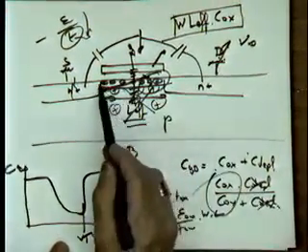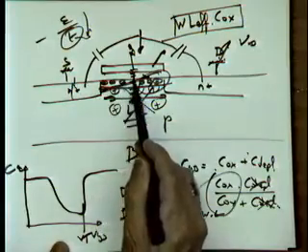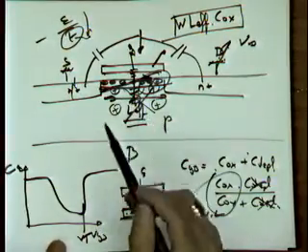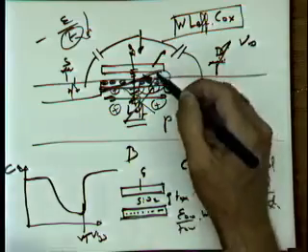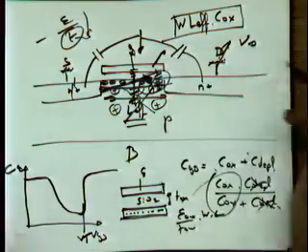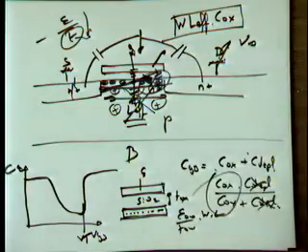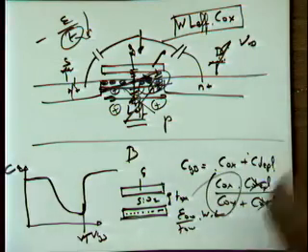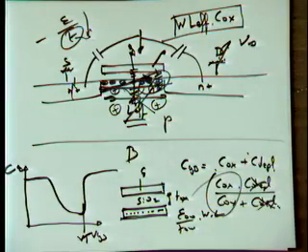So you can look at this as having now a conductor that basically extends partially underneath the channel, and then some other capacitance that goes places. Now, obviously it's not abrupt. This is the extreme case. When you go from linear to saturation, how the capacitance is going to go between source and drain is gradually going to change. It starts with half at source and half on the drain.